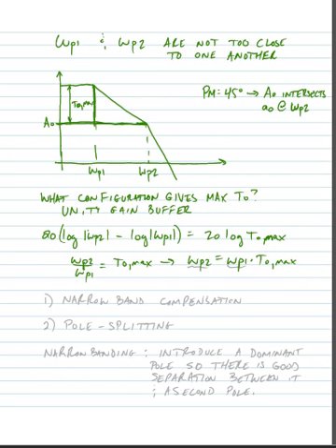Now, of course, what this all comes down to is we're going to try and design our operational amplifier to meet these kinds of considerations. So we will try and set omega P2 and omega P1 according to this formula. There are a couple of different ways that we have of doing this, and they're both different types of compensation.